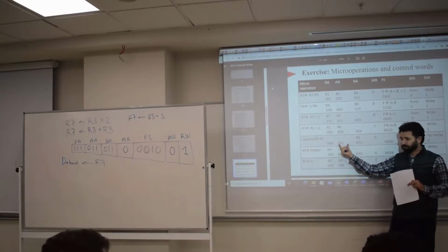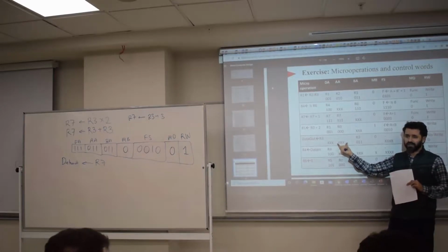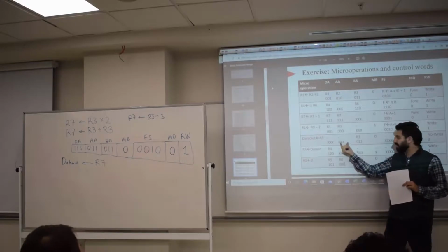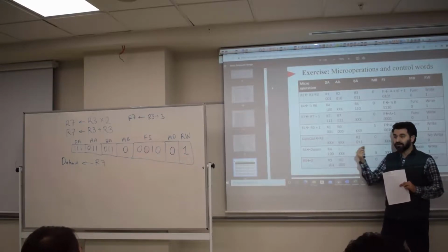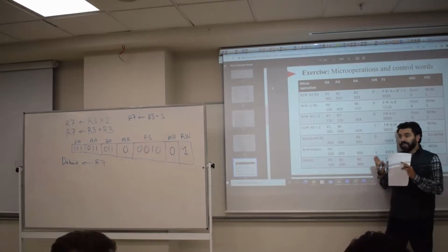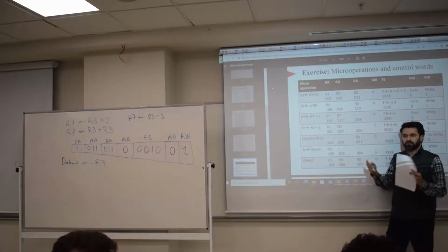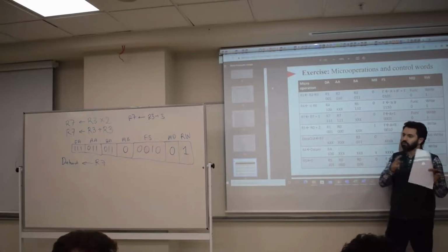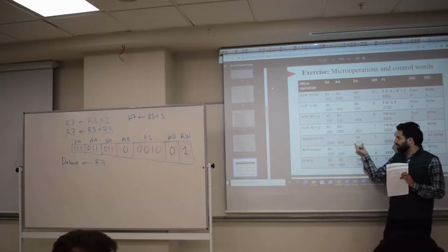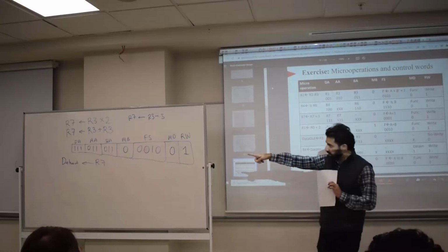But in general, in practice, you probably have an address here. The address is of course not 3 bits. 3 bits is the register address. But that register contains some data, right? That data is not user data. That is the memory address. Somebody has written that register sometime in the past. So you can use that address. And the data that is stored in R3, but in our case is of course R7.